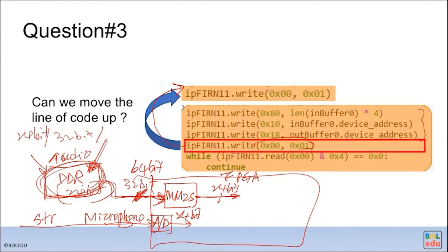Or you may want to fully pack the 24 bits. In that case, when you access the DRAM, you can only access in 64-bit quantities at a time, so you need to extract each 24-bit piece and do some processing.